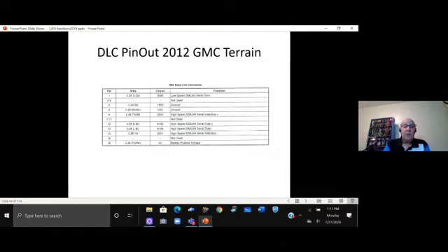Anyway, so if you look down pin 6, high-speed GM LAN, serial plus. 6 mates with 14, notice high-speed serial data minus. 12 and 13 mate. 12 is plus, 13 is minus. So when you look at these automobiles, and you teach the diagnostic routine, teach the student to look at what works and what doesn't work, and then go into the wiring diagram.